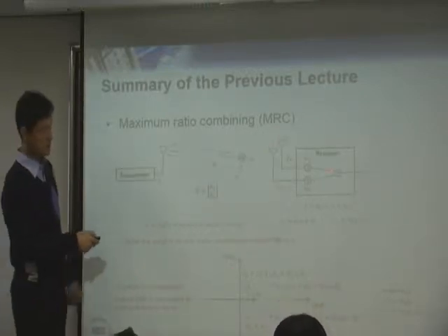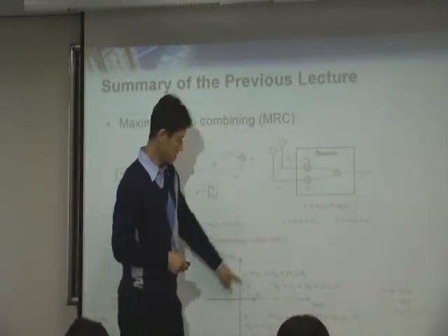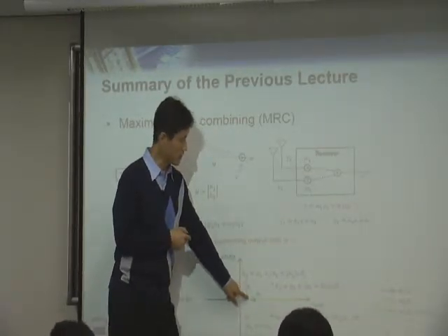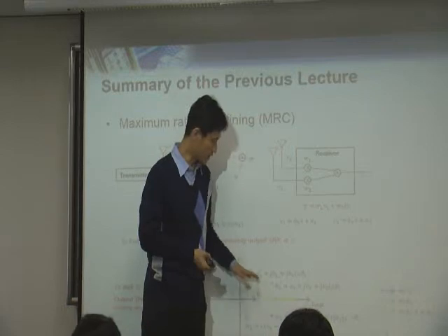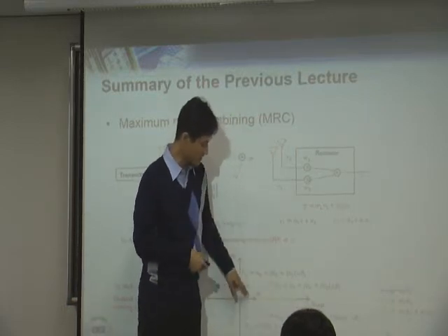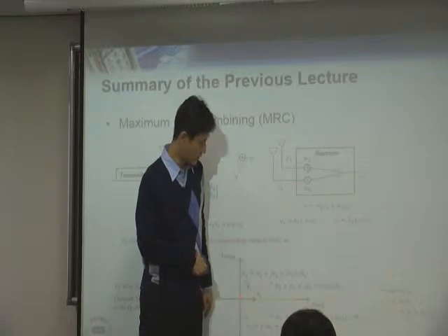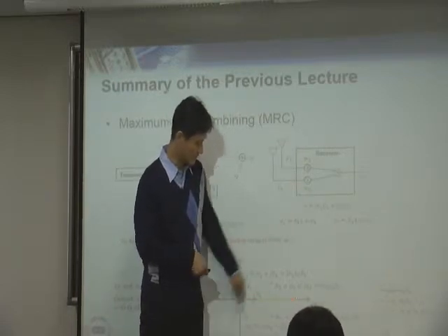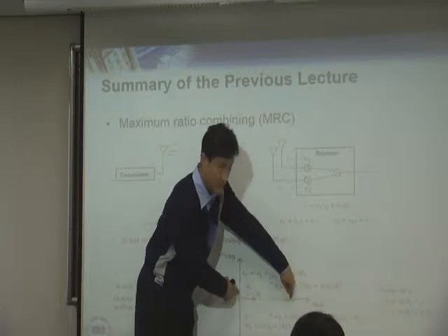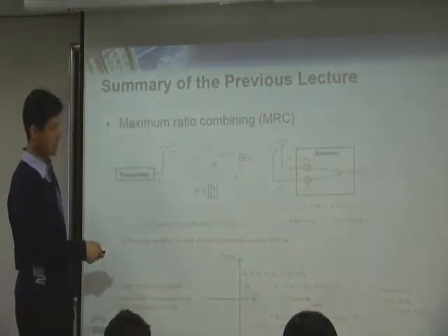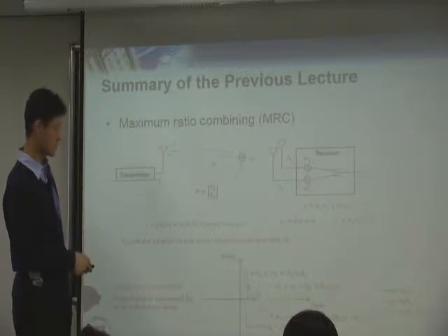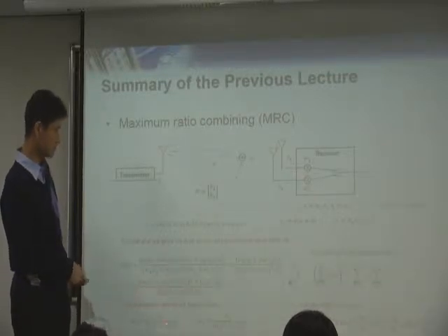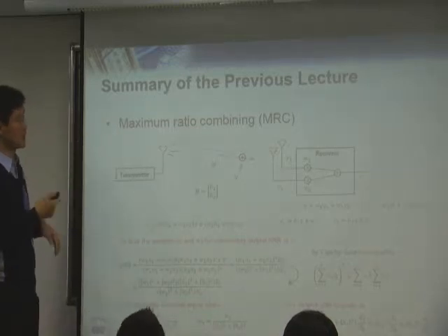You see that the output right here is purple, and the output right here is green. If you add them together now, purple and green are aligned on the same real axis. So when you add together, the total sum is going to be yellow. You see that the length of the arrow is now maximized by making these two aligned. And in order to make alignment, W1 and W2 have to be chosen this way. Okay, that's the concept of maximum ratio combining.